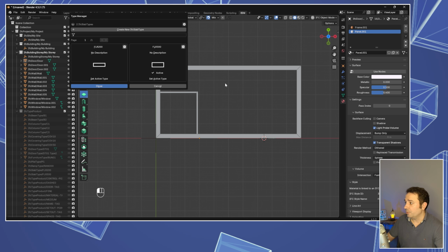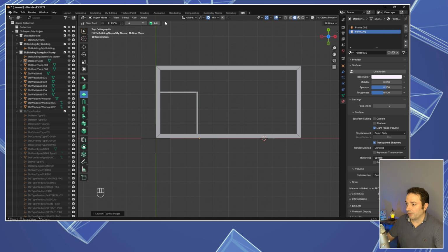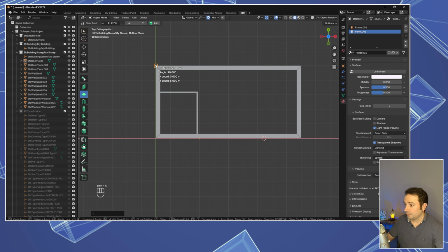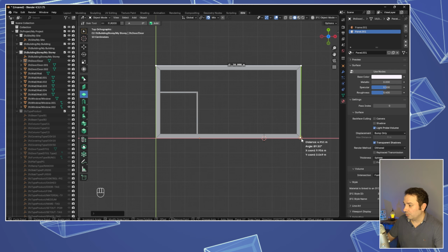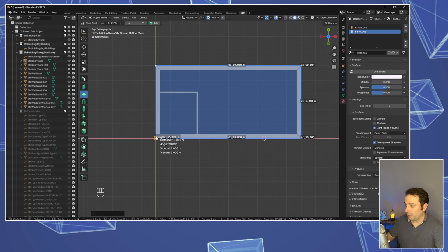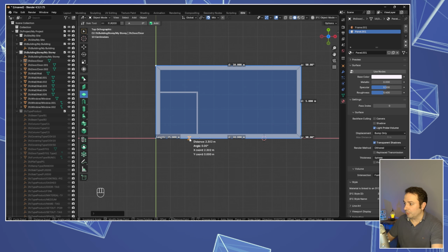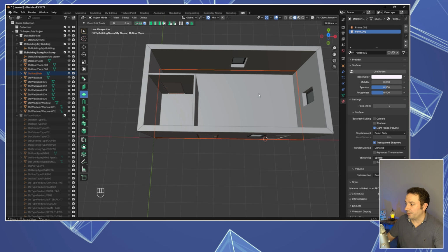So you're going to end up using, once again, the parametric feature of Blender. I'm going to select 201 and now press Shift A. And now we have the possibility to use a polyline to define the perimeter of our slab. I've already done a relatively good job. I'm going to press enter, and you can see that now the slab is here.